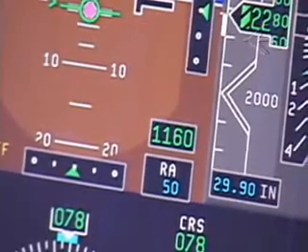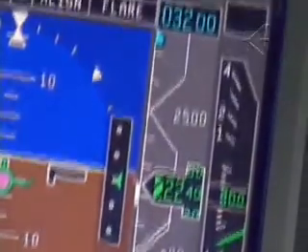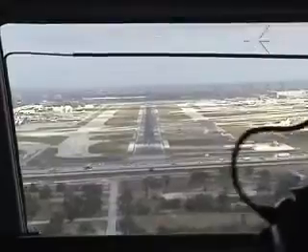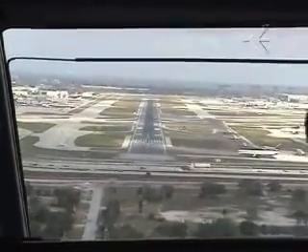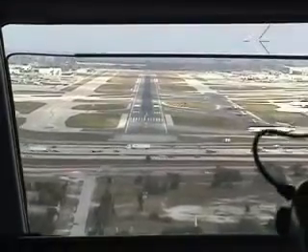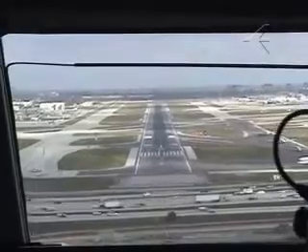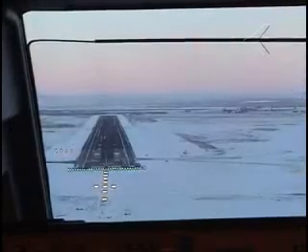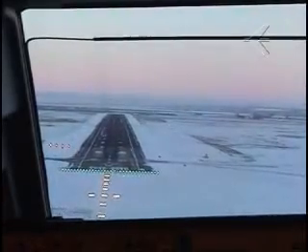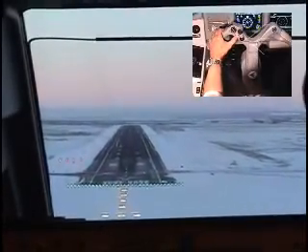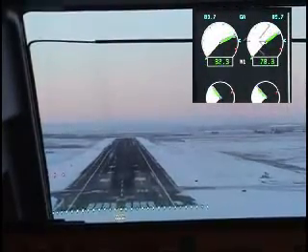Flight crews must remember that when ILS critical areas are not protected, ILS beam quality may vary due to vehicle or aircraft interference. That is supposed to happen when weather minima are not CAT 3, but CAT 3 restrictions are not being followed. Therefore, when training Autoland operations in CAT 2, CAT 1 or visual conditions, closely monitor Autoland performance and be prepared to disengage autopilot, manually land the aircraft or go around.